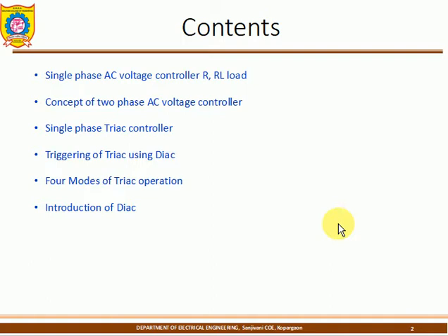In the R type of triggering circuits, when an AC power supply is applied to the SCR, it will conduct only half of the cycle. The remaining half of the cycle is not conducted. It is naturally commutated, because the supply varies between phase and neutral. When you use the TRIAC, conduction happens in the negative half cycle also.